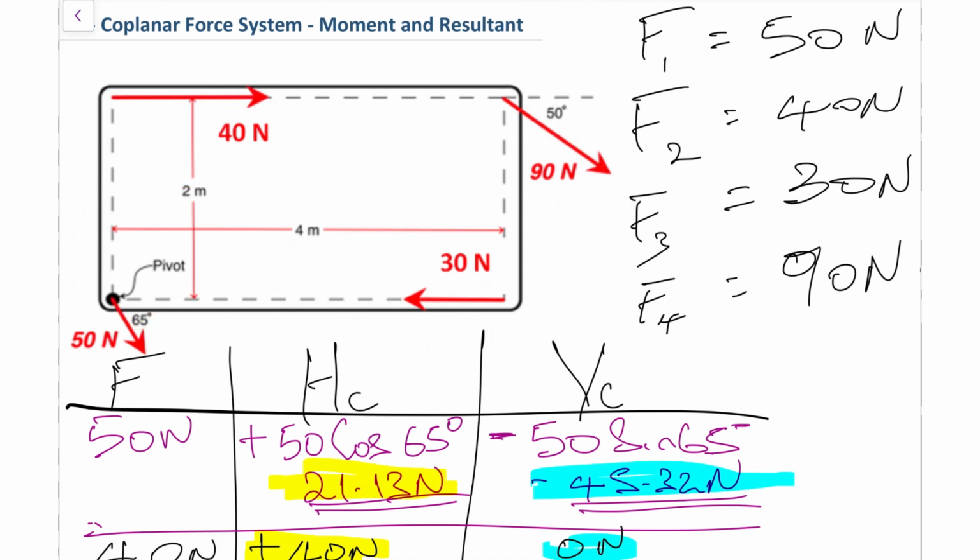So now for the vertical components, you will see this path I'm highlighting in green, and the line of action going across to that same pivot point has to be at 90 degrees, which is right there. So it means that if we know the vertical force component, which we do, we would have to multiply that force component by 4, because that's the length of the horizontal distance, which happens to be perpendicular to the force.